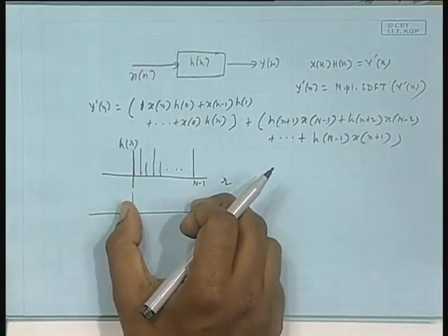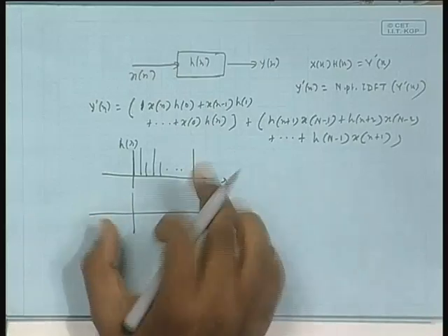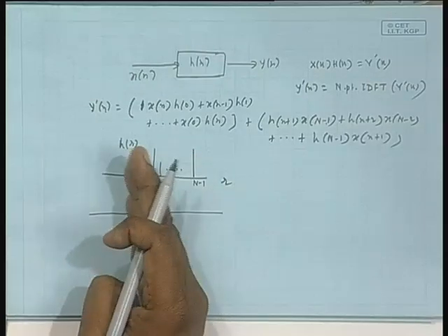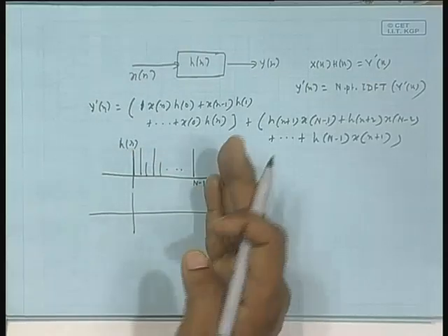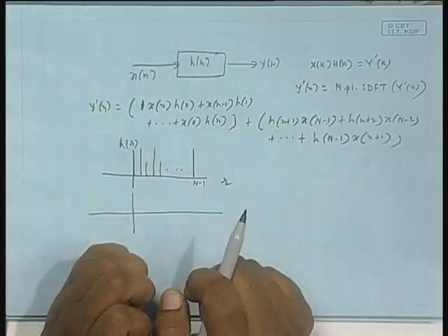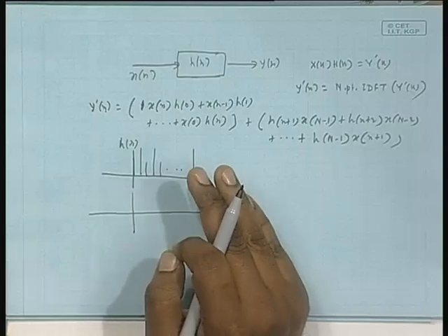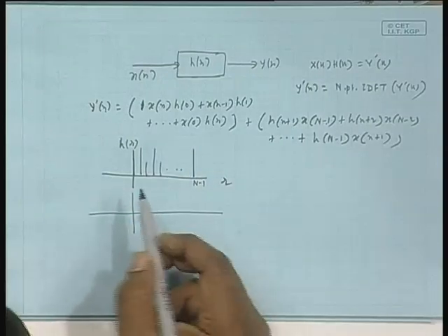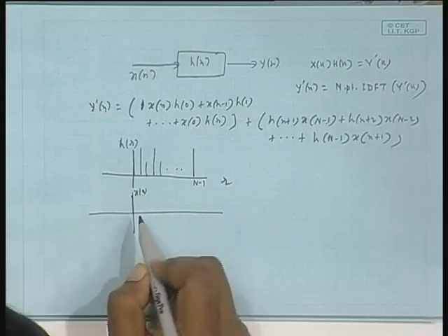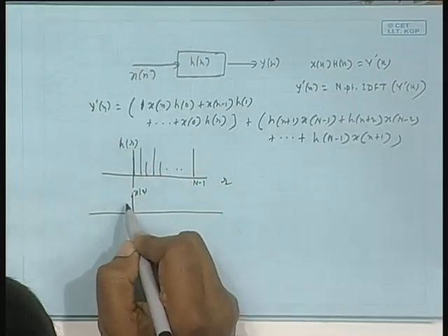Then what I will do, whatever I have for x n, x r rather, I will make it periodic, fine, and then I will shift, reverse it, and then shift it by an amount, and then chop off portion to the right of this, to the left of this, and sample wise multiplication addition. So, for the time being I will start with 0 shift, then 1 shift, 2 shift. So, 0 shift only. If it is 0 shift, what I get here is x 0, then to the right I had x 1, x 2, x 3 like that, because of reversal it will go this way,